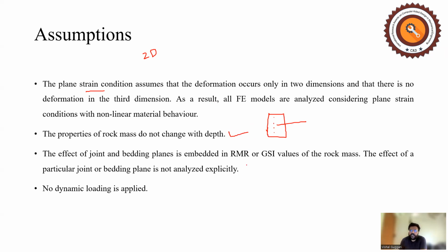And the particular joint or bedding plane is not analyzed explicitly, and these joints or bedding planes or the geological distribution have been considered in the GSI and RMR values. And again, the static load has been applied. There is no dynamic load applied on each model.